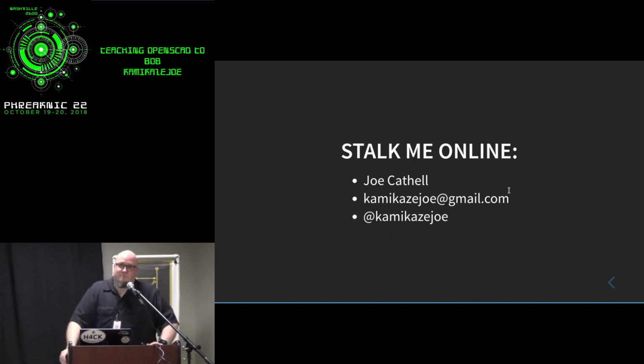Yes, sir. Just a comment, keep in mind everything is unitless. When you design your object in OpenSCAD, you're not talking inches, millimeters, or miles. It could be light years. It's whatever your printer... Yeah, that's an excellent point. Everything in OpenSCAD is unitless, even though I had figures there. They're just abstract. It doesn't actually get any kind of defined value until you're actually trying to print it out.